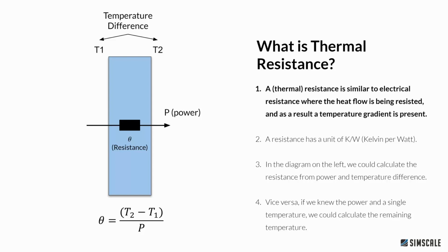Unlike this plank of wood, we can have power going the other way. If we had a component with power being applied into its center, we could have power going out through the case, out through the board, as mentioned before, and out through the sides. So we need to apply this to CFD, should I say. We need to have these resistance values.